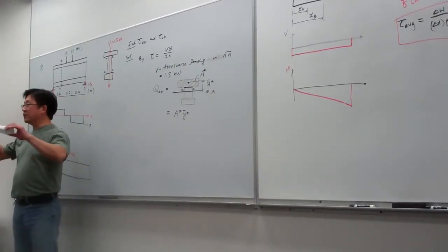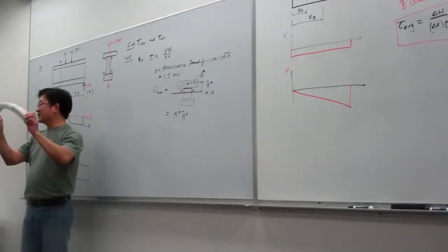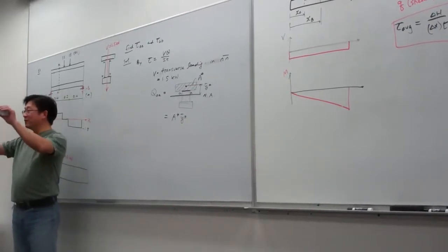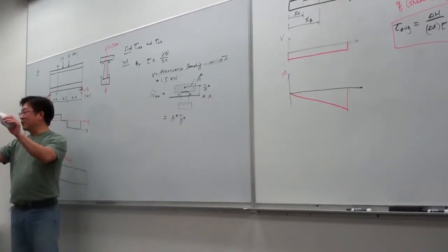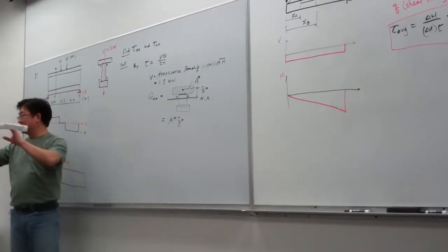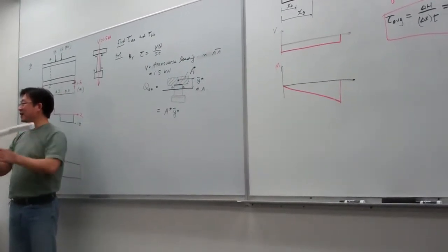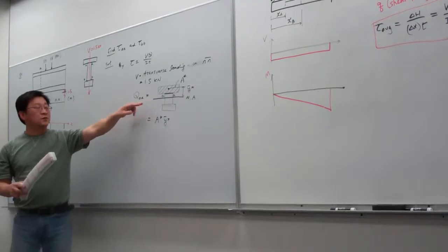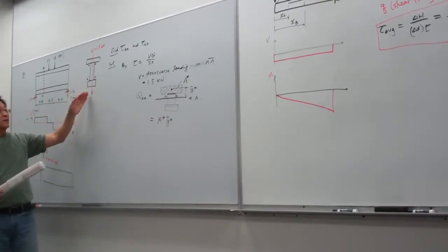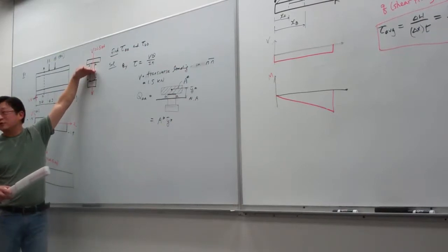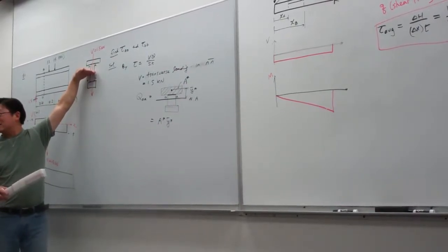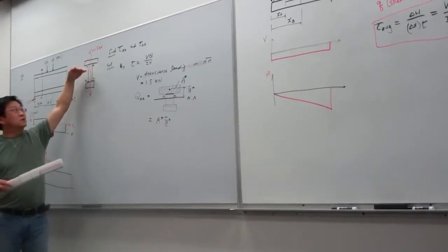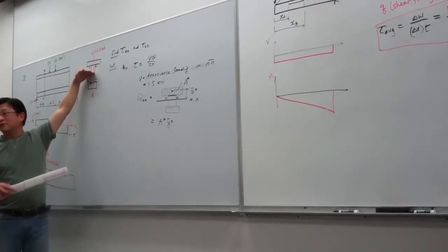Again, for this example, our beam is bending over like this, so the neutral axis is the horizontal one. When we bend like this, that induces transverse loading, which is vertical. So the quickest way to identify the orientation of the neutral axis is to simply determine the direction of V, then the neutral axis should be perpendicular to V. That is the quickest way. You don't have to think through the derivation from the very beginning. You simply take this rule of thumb.